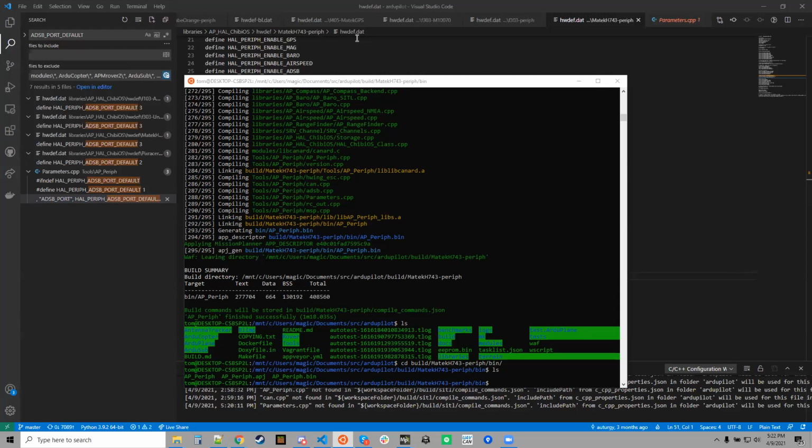If we extended the AP file system to have temporary file system support, then you could MAVLink FTP a firmware to the autopilot into tmpfs, and then send a MAVLink command to say, now please upload that file to all of the nodes, all compatible nodes. It would have to know that the node was compatible with that firmware by using probably the string identifier, along with the board ID. That would provide quite an easy way to do a mass update of your ESCs, for example, because I think otherwise it'll be quite painful.